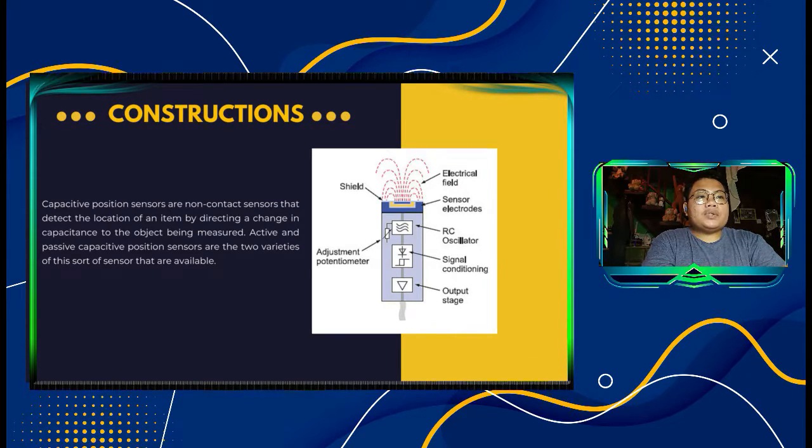The capacitive sensor provides very high resolution, matched only by the laser interferometer, and the common resolutions range from 0.1 nm to 50 nm. Operating ranges are generally less than 3 millimeters. So technically,